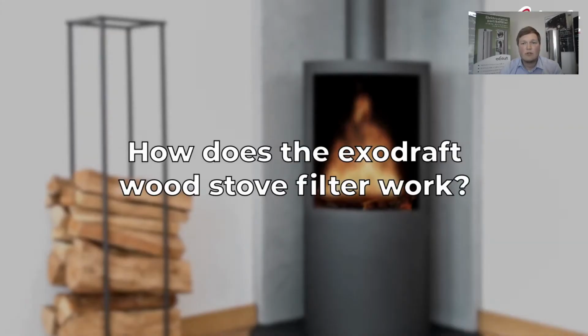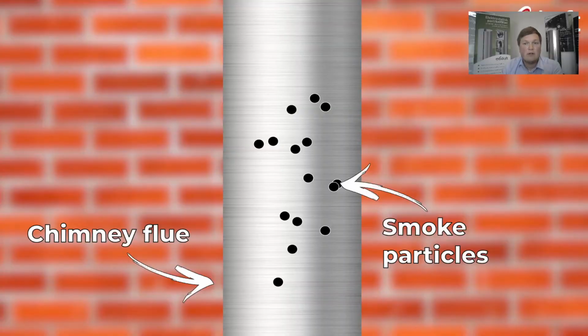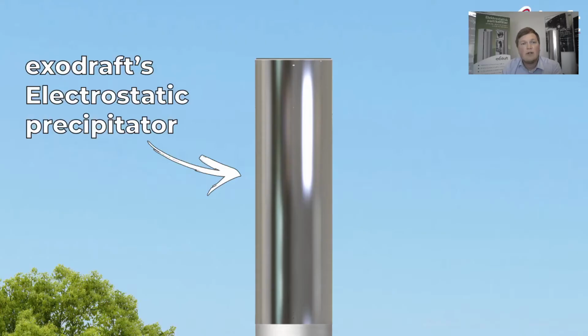So where can electrostatic filters actually be used? Our ESP10 can be mounted on any existing stove. It must be a closed fireplace with up to 10 kilowatt of heat output. The smoke particles will travel up inside the chimney, and it actually doesn't matter what kind of chimney it is. The filter will be mounted on the outside because there the flue gas is as cold as possible, and many secondary particles already have condensed to solid particles, and it's visually matching a steel chimney pipe.